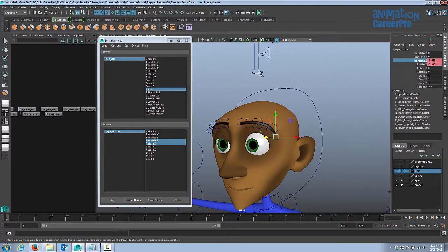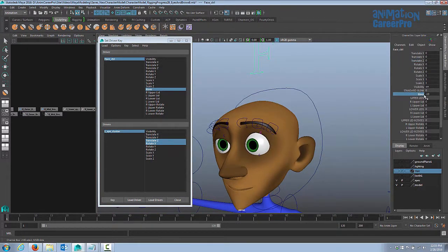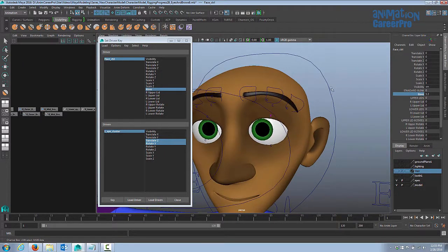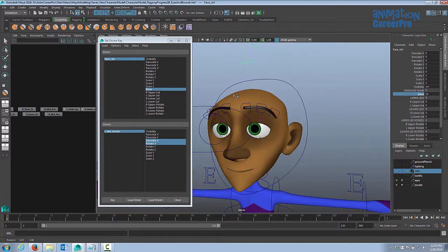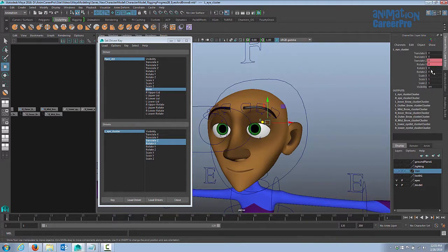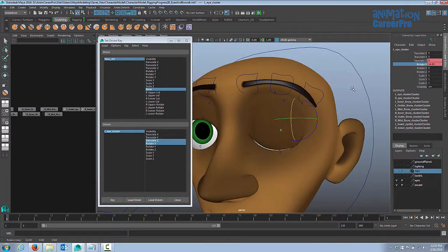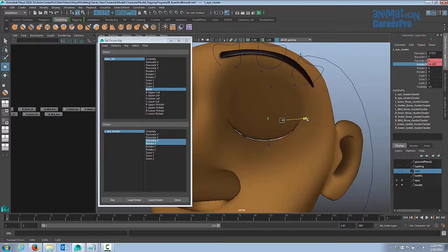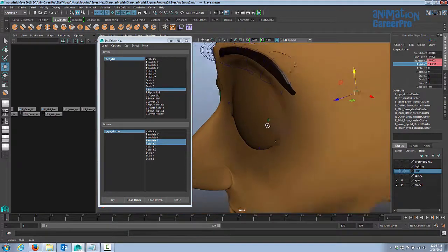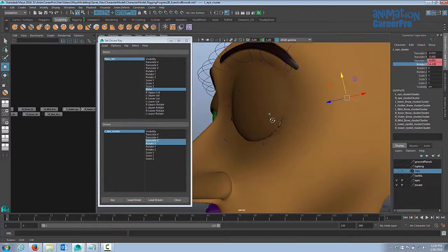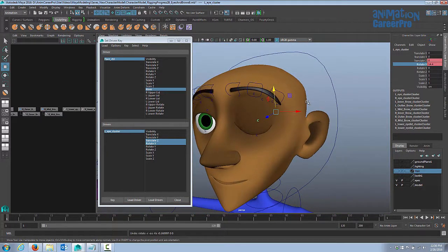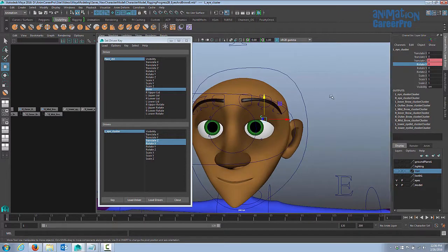Now if we select the face control, we select our blink attribute, and if we drag, we should get the eye going from default to wide open. Okay, so that's set. Now let's drag the blink attribute to 10, and we'll select the cluster again, and now let's close the eye. It would be great just to translate that cluster over a little bit, just to get the eye to shut perfectly, and maybe even translate it down. So I'm feeling like maybe I should include all the translates in this set-driven key. So I'm just going to undo that. Let's make sure our cluster is back to 0.